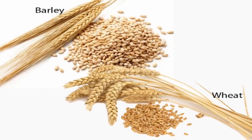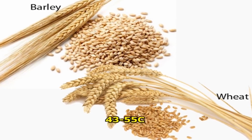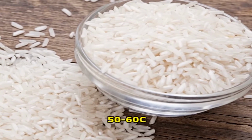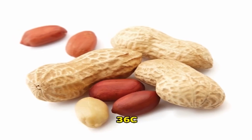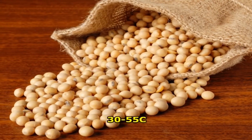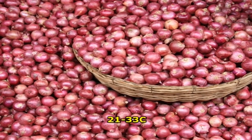In case of wheat and barley, the temperature is 43 to 55 degrees centigrade, while for rice it is 50 to 60 degrees centigrade, for maize 40 to 45 degrees centigrade, groundnut 36 degrees centigrade, soybean 30 to 55 degrees centigrade, onion 22 to 33 degrees centigrade, etc.